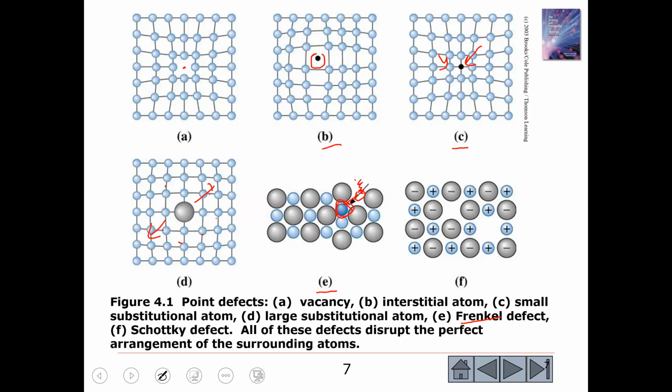So overall, the charge balance is neutral because the atom has not ejected or left this material. It is inside this material, but a localized charge disruption has happened. So we call it a Frenkel defect, when an ion moves from its place and moves to another place.